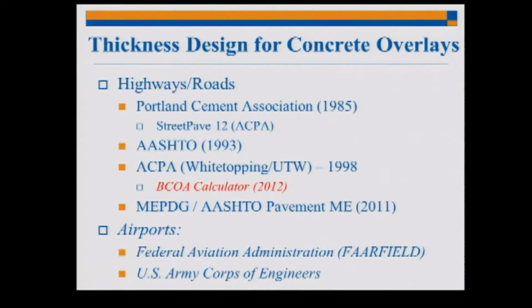It wouldn't be the best one to choose, but it does do some types of overlays. And on airports, you can use some of the Federal Aviation Administration software, and that's free. The Portland Cement Association has an old overlay guide, but more recently it's been republished and updated by ACPA as StreetPave 12. So these are some design methods you can go out and use. Some of these are free, some of these cost a little bit of money.